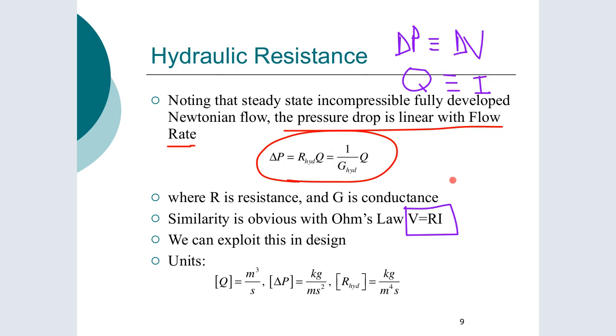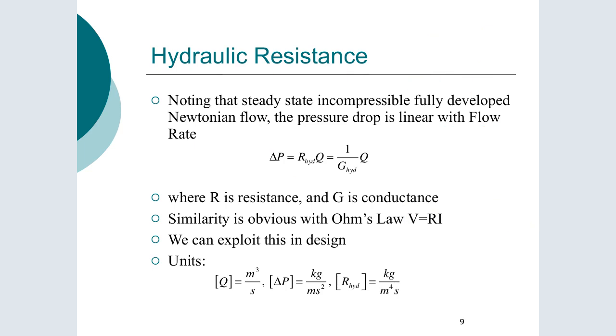So we have this requirement of a constant pressure drop, because if the pressure isn't dropping in a constant manner, then it must be accelerating. And in the inertia region, the entrance region, it is accelerating. As you move along the streamline, the flow is changing, the velocity is changing its magnitude. So this really only works in the fully developed region.